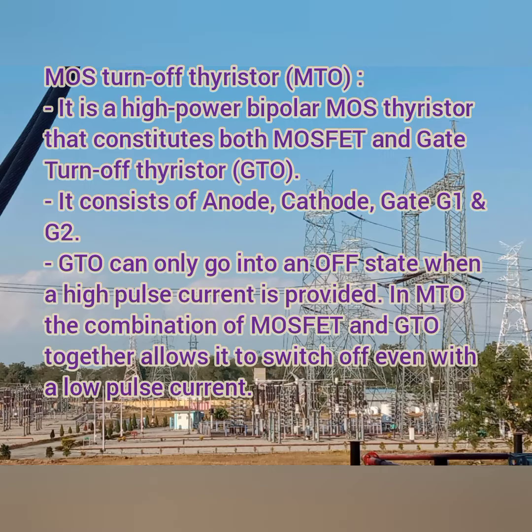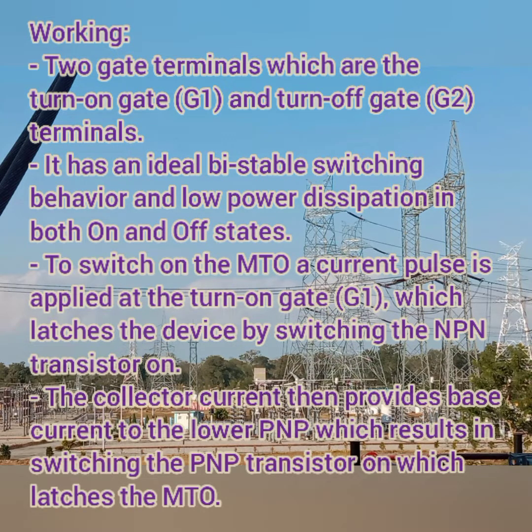These MTOs work with two gate terminals, which are gate 1 and gate 2. Gate 1 is for your turn on and gate 2 is for your turn off. It has an ideally bistable switching behavior and low power dissipation in both turn on and turn off states.